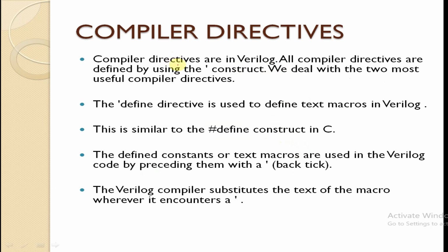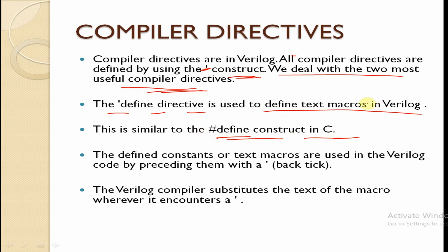Next, coming to compiler directives. So compiler directives are in Verilog. All the compiler directives are defined by using the tick construct. We deal with the two most useful compiler directives. The tick define directive is used to define text macros in Verilog. So this is also similar to the hash define construct in C.